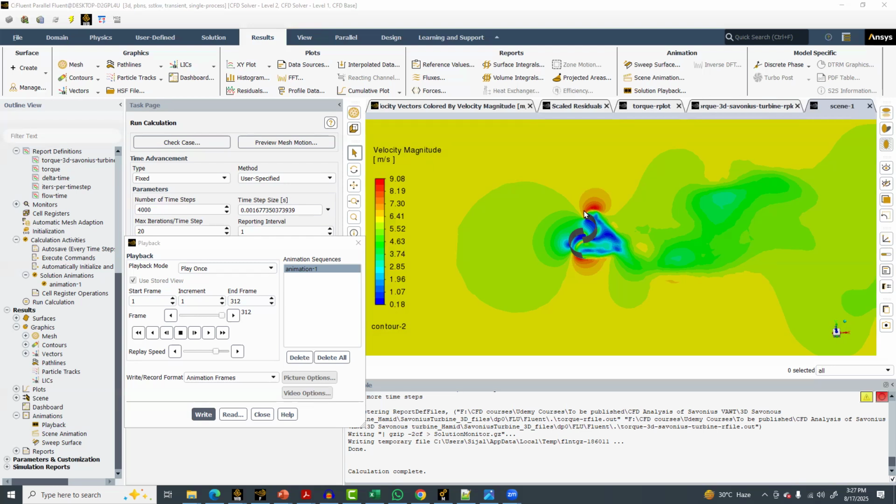And thirdly, I would say that dynamic meshing will have a lot of problems, like negative volume. You have to set them, and you cannot run the case with this time step. You have to put the time step at maybe 10 to the power minus 6 to stabilize the solution. The data from both cases will be the same, and the recommended way of running turbomachinery cases with a fixed RPM is sliding mesh. Okay, so it's sliding mesh, not dynamic meshing. Okay, thank you, Cyril. Do you want to run the case with dynamic meshing for some particular reason, for some particular case?